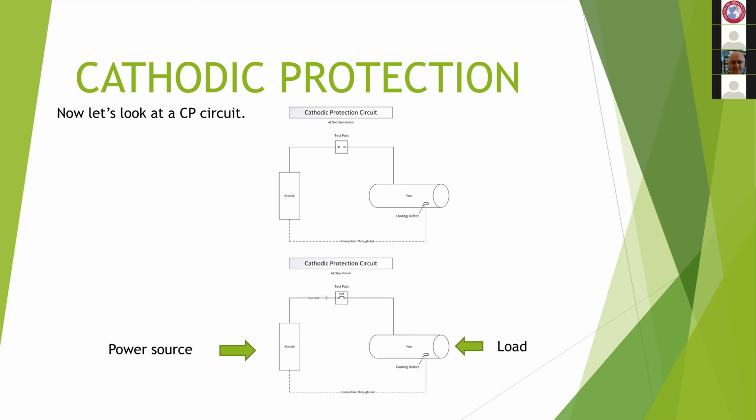Rather analogous to if somebody is hiding behind a tree and you direct a jet of water at the tree, they will be dry, because the water will hit the tree and then go around the tree on either side and meet up at the back of the tree. So stones in the ditch and obstructions like that can affect your cathodic protection effectiveness.